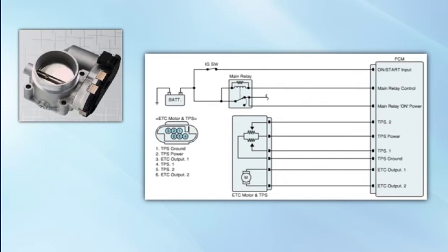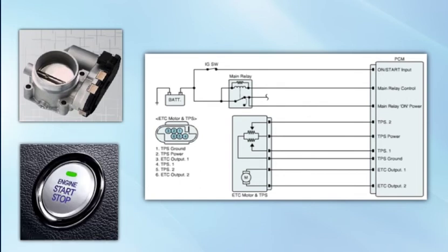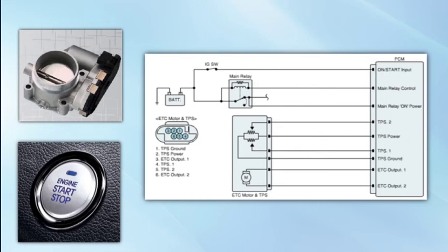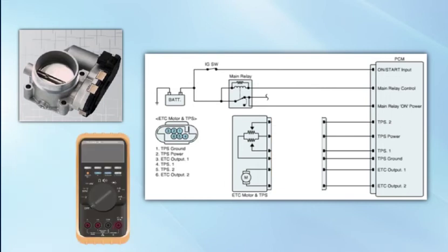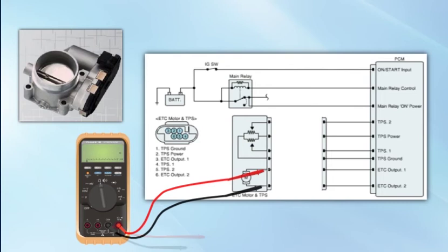To check the resistance of a sensor or component, turn the vehicle power off. Isolate the component or the portion of the circuit to be tested. Attach the test leads to the correct input terminals on the DMM to measure resistance. Set the mode switch to ohms. Connect one test lead to each end of the electrical component or section of the circuit to be tested. Note the reading on the display. Compare the reading to the specifications in the service manual.